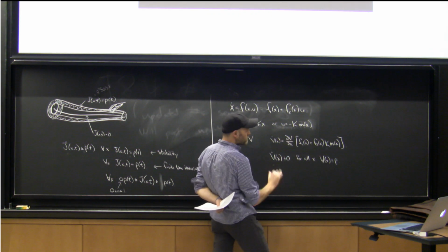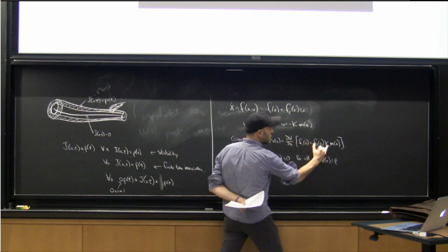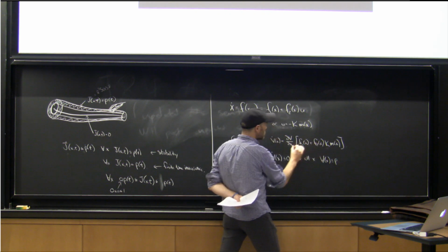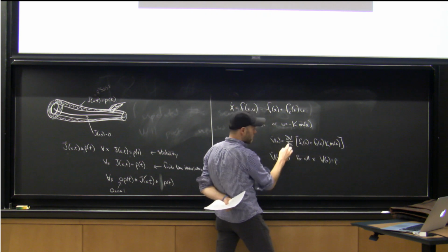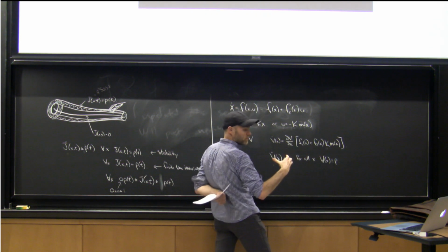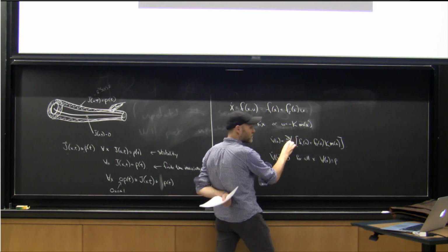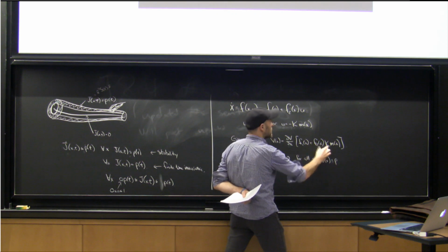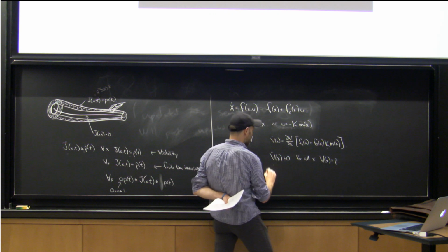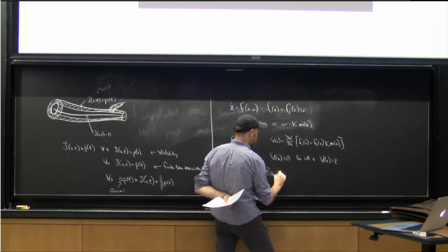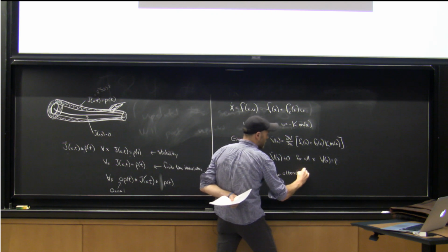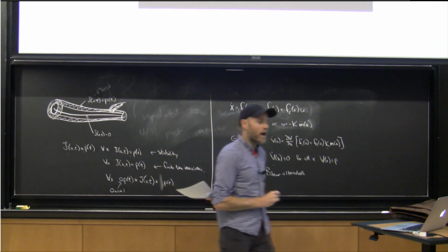So in practice, there's a handful of ways where you pick a controller K. For instance, you start with LQR. You search for the biggest Lyapunov function that'll prove the biggest basin of attraction. And then you lock in your Lyapunov function and ask, could I have found a different K that would have proven an even bigger region of attraction? And you alternate back and forth. So you get bilinear alternations. And this can make a big difference in practice.